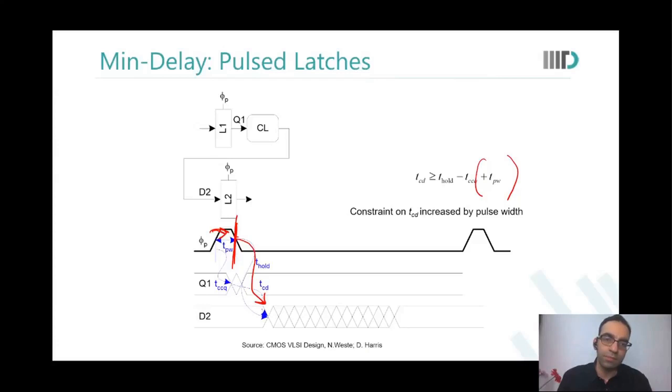So that after the falling edge, my data should be stable for T hold. Yeah. So let us say it got triggered from the rising edge of the clock at L1. So tcpq plus tcd of the combinational logic should be greater than T hold. Where is this T hold coming from? Not the rising edge of phi, but from the falling edge of phi. So pulse width. The sampling edge for a latch is the falling edge. Yes, sir. That is where tpw gets added.